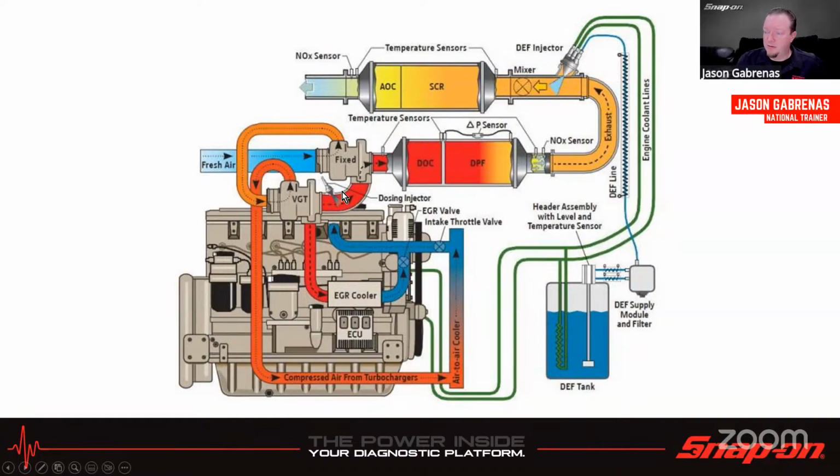Dosing injector, which is going to be spraying diesel fuel into the exhaust in order to light the DPF up and get it to the proper temperature so it can regen. There's multiple temperature sensors along the way, so the computer can monitor how things are working along the way. And then we get down to our SCR system down here, and there's a couple NOx sensors, inlet and outlet NOx sensors. There's also the DEF injector, which is the diesel exhaust fluid.